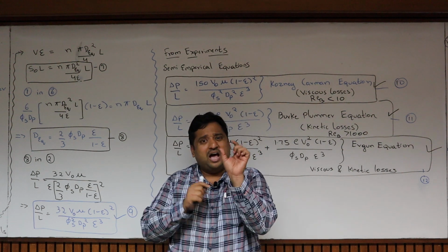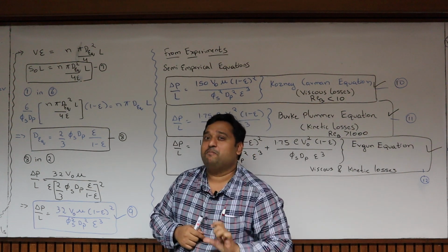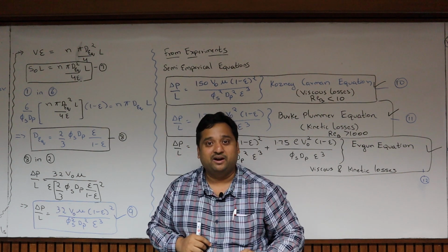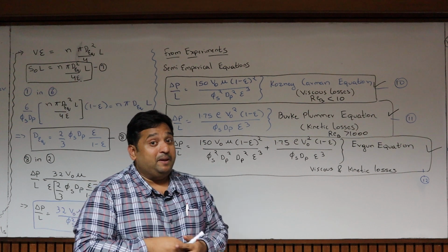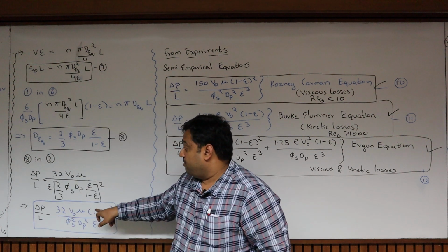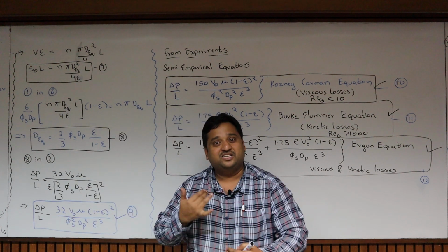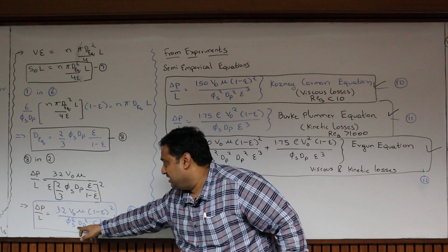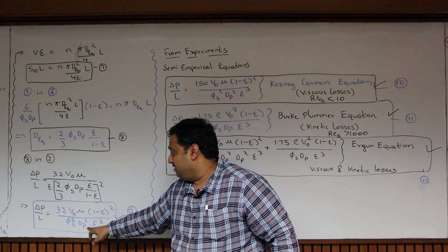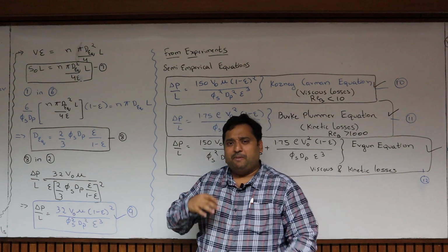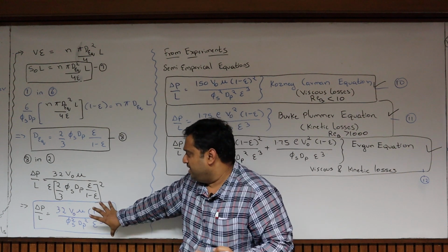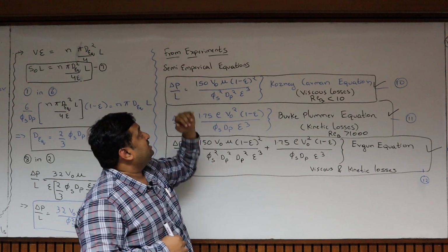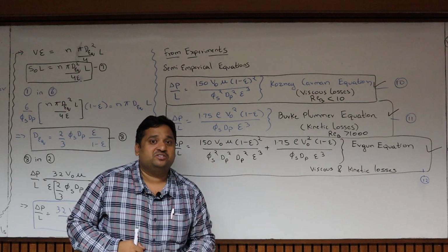Not straightforward, we have to do some changes. As I told you, I have taken only one single channel, which is not appropriate. I have to consider all the channels available in the hypothetical bed. But people have done some experiments. We cannot straightforwardly use this equation. They conducted different experiments, using different velocities, different viscosities of the liquid, different sphericities and different diameters of the particles. By conducting these experiments, they found out this equation cannot be used straightaway. Instead, you have to use this kind of semi-empirical equations.